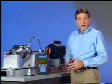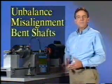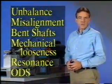But here, we will use static phase measurements to diagnose machinery conditions such as unbalance, misalignment, bent shafts and cocked bearings, mechanical looseness, resonance, as well as a brief overview of operating deflection shapes.